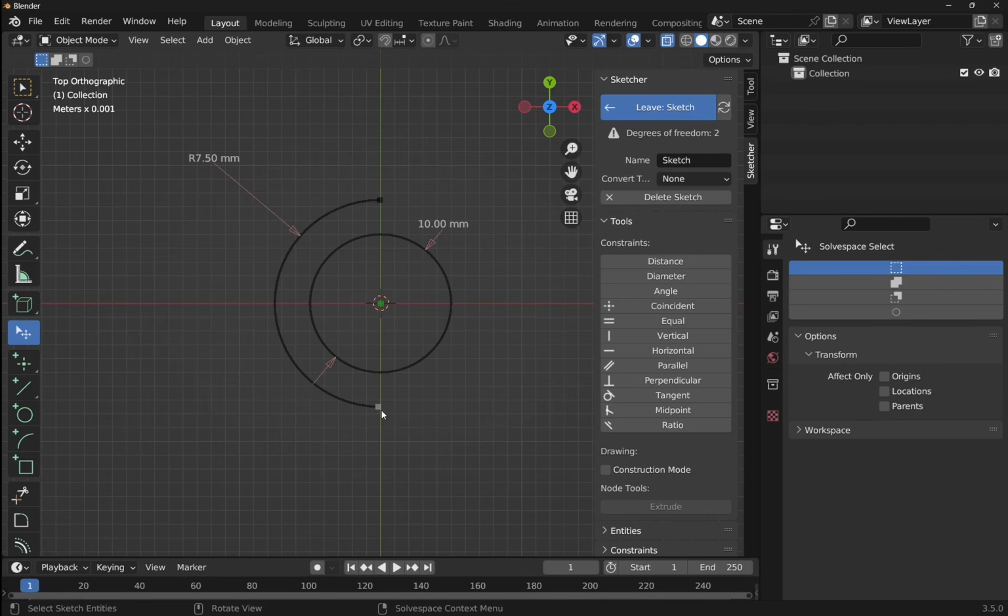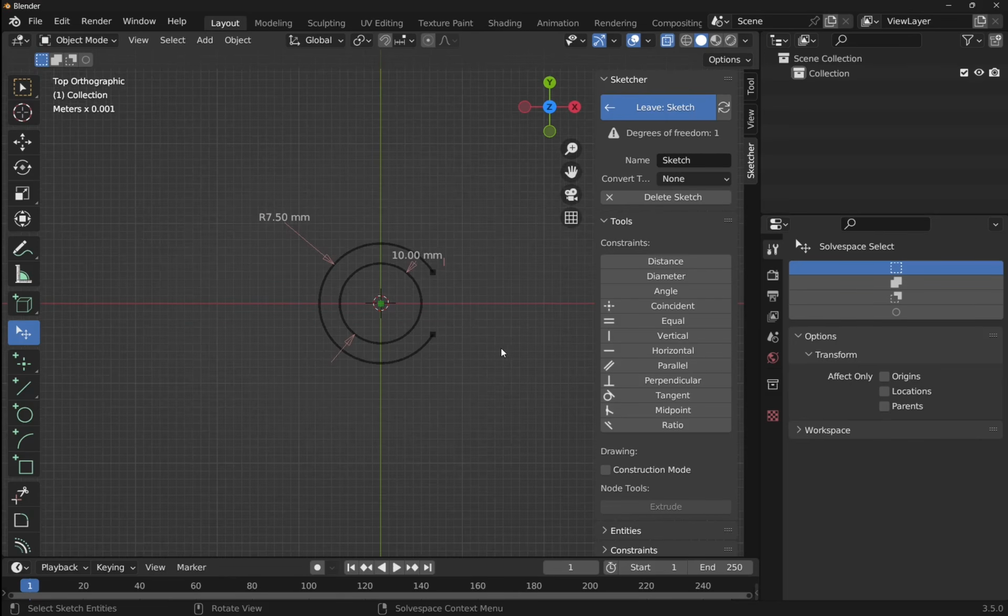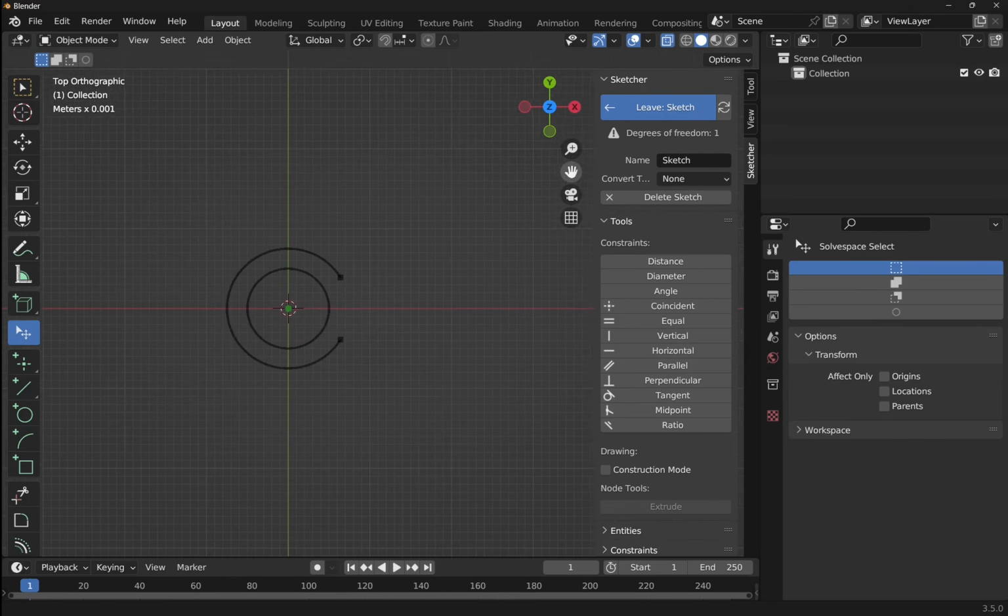And now I'm going to take these points and bring them around to about here. I'm going to take this point and this point. So shift click them. Click one first, hold down shift, click the other, and put them in vertical constraint. So we've got that there. They will move with that one. Let's zoom out to see what we got and move this off to the left.